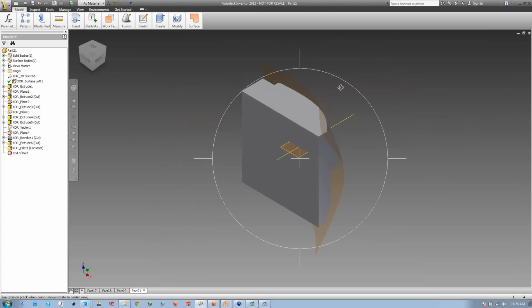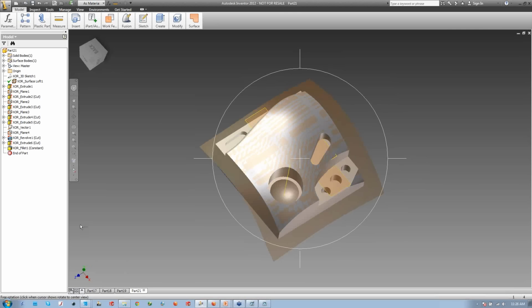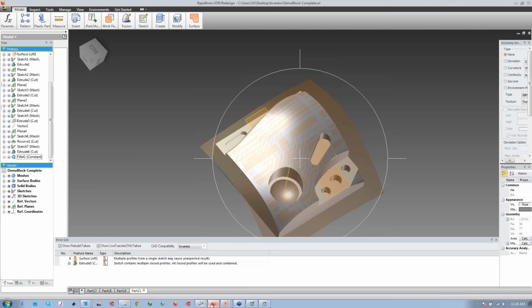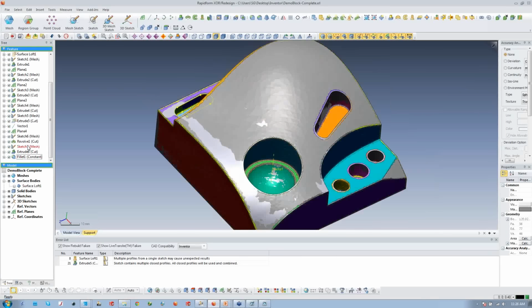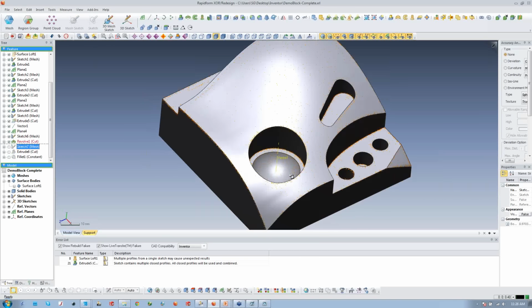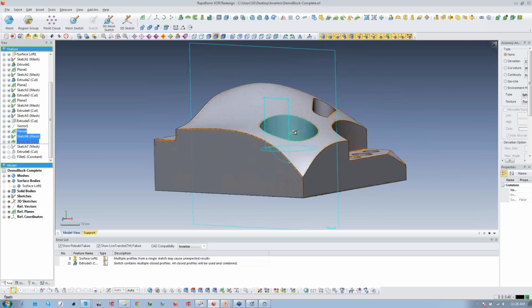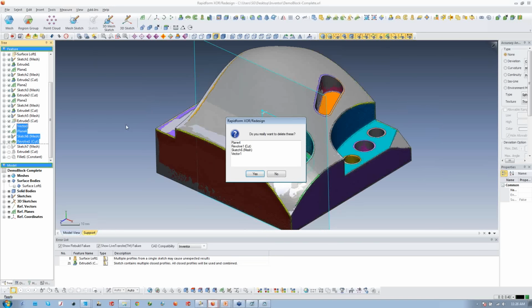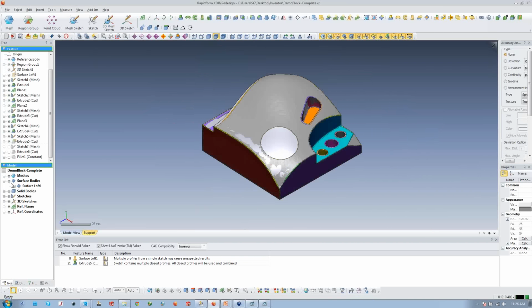What I'd also like to show you is a little bit about our quick modeling workflow, which creates parametric geometry with just a few clicks of a button. And this also live transfers directly over to Inventor. So if we take a look at this cylindrical feature with a sphere at the top, we know that this has a center line and is probably a revolution. So if I delete that feature, I'll go back and remodel it using our quick modeling workflow.